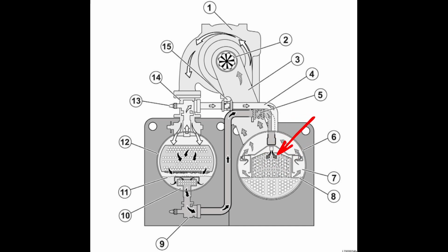So the size of our chiller doesn't have to change a whole lot. It may be marginally larger. We maintain the same relative efficiency values, but we reduce our total refrigerant charge dramatically, like heavily reduce the total charge required for a hybrid system. And there's this set of baffling in here that prevents our spray rails from being able to spray directly into our suction side of our chiller, which would be really bad.